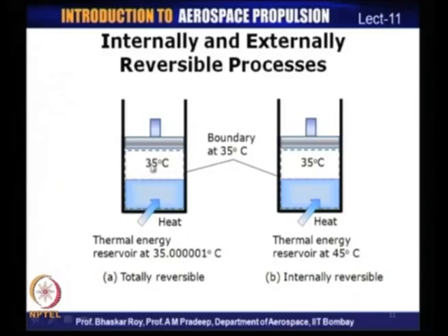Well, not really steam, because temperatures are pretty low, but it could be some other system which has a liquid phase and let us say a gaseous phase, and there is a heat transfer across the system boundaries, making this process a constant pressure process, and consequently it is also an isothermal process. And so, as the pressure is a constant, of course, we allow the piston to change its position, and that is why we can maintain the pressure as a constant.